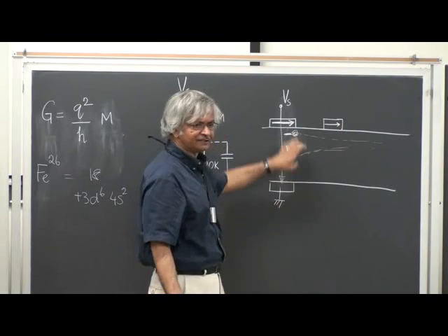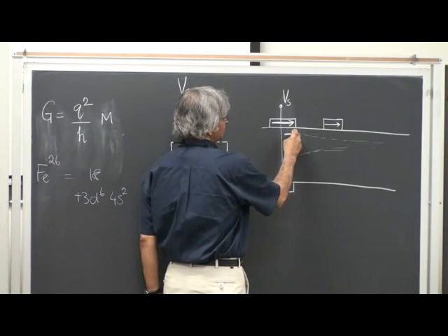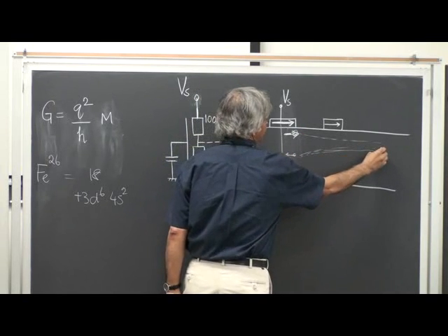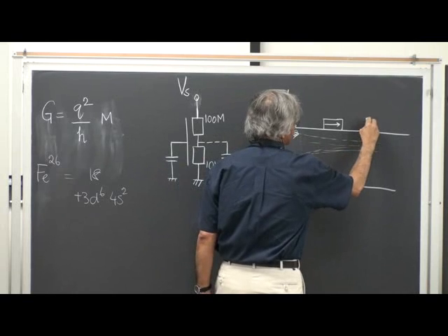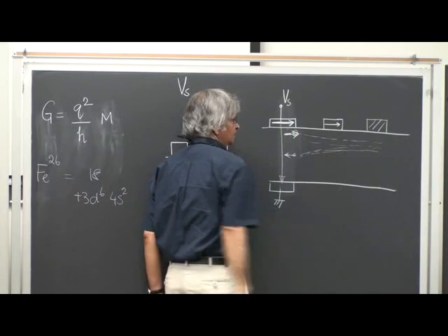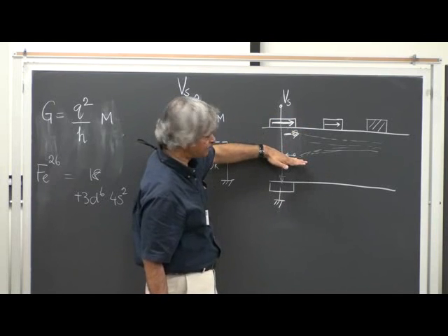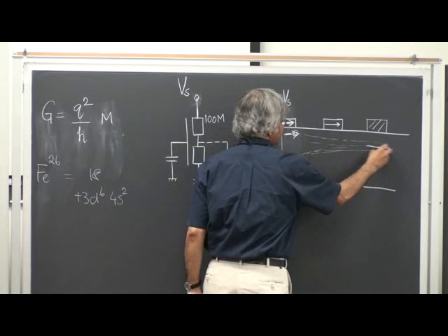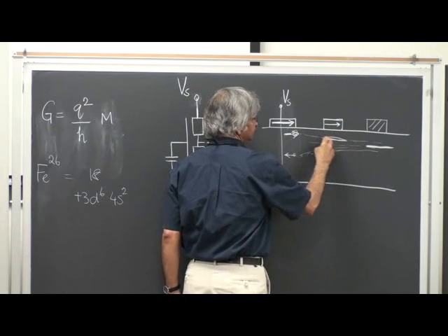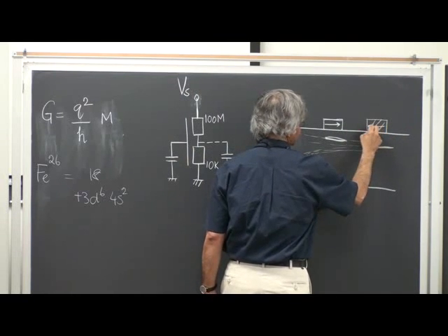So it's almost like in a bipolar transistor. So a little bit like minority carrier spreading out, if you're familiar with that. But anyway, the point is that if you looked at spins of one type, they're spreading out this way. Spins of the other type, they're going this way. And if I put another contact here, which is non-magnetic, it would measure the average chemical potential. Like you could think of these as the quasi-Fermi levels for one type of spin and another type of spin. And this one would measure the average value. On the other hand, if you put another magnet here, it would measure that value. And if you had put a magnet in another direction, let's say pointing this way, then you would have measured